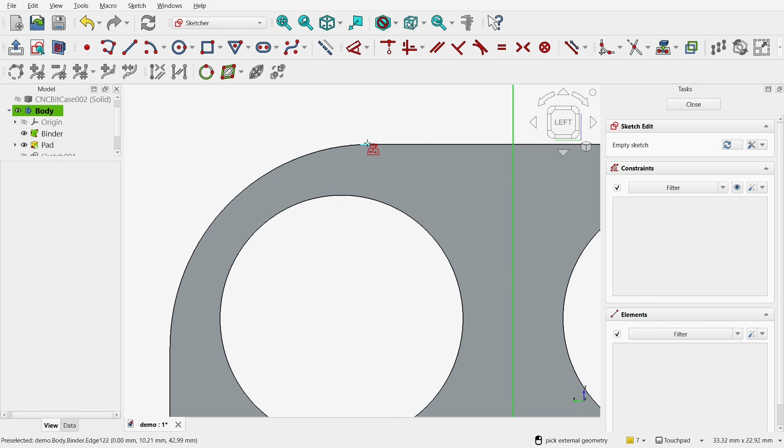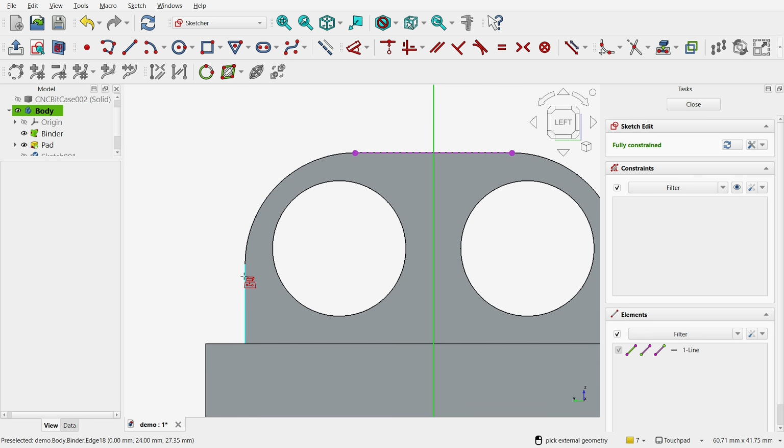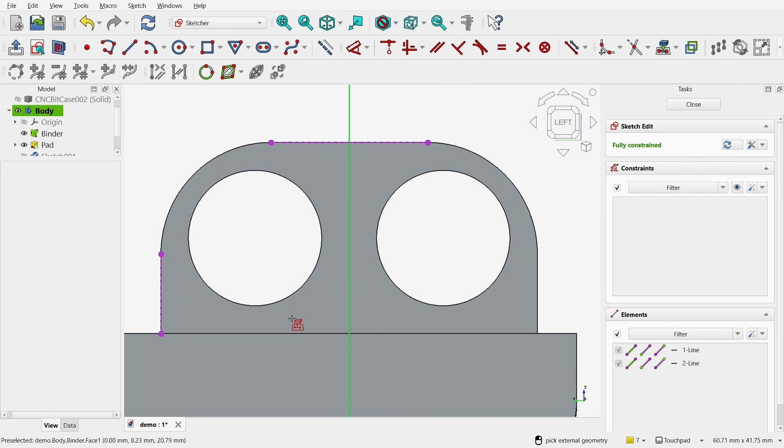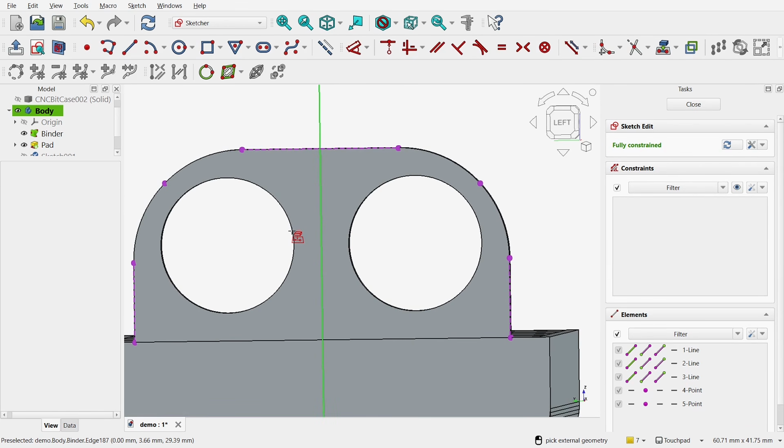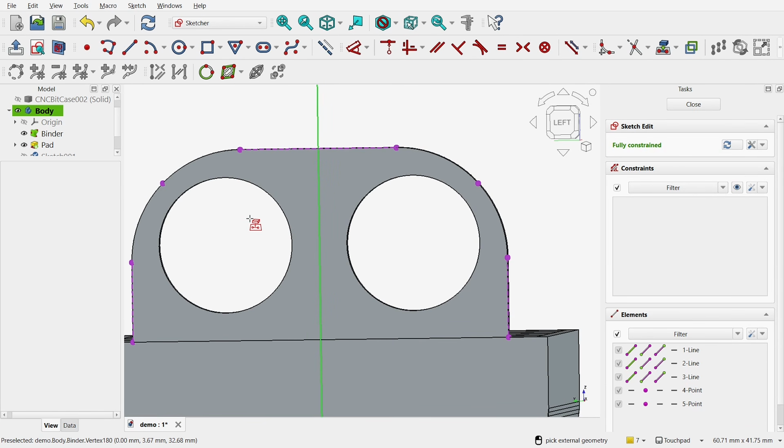Let's import some geometry. So I can import this line here, look at that point, and maybe this line, and this one as well. Points on the arc, some random points there. With the circle, we have no center point. So when we create circles, we create it via the center point and then set dimension. These are individual vertices that run around here that are connected to those lines. So to constrain a circle in here, we really need 3 points.